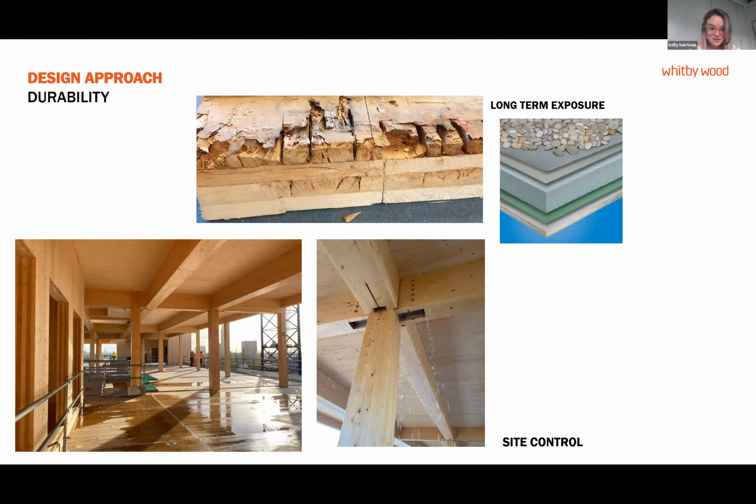The risk areas are at the joints, and so the joints all need taping, and you can see that they're all taped up on here, and the edges where you've got the end grain. So you can see from this photo at the top that the grain is going through each lamella. That grain is a capillary basically that takes water through a tree. And so as soon as it sees water, it starts sucking it up. And so you don't want it to get in the end grain, basically. You need an edge protection.